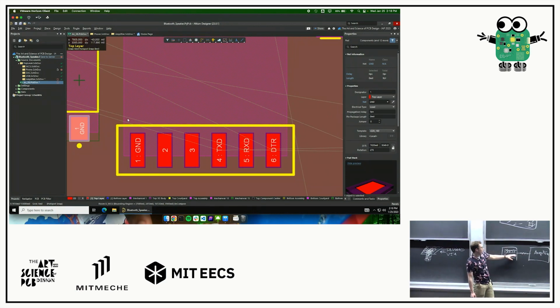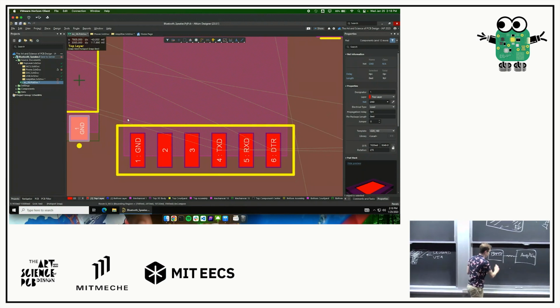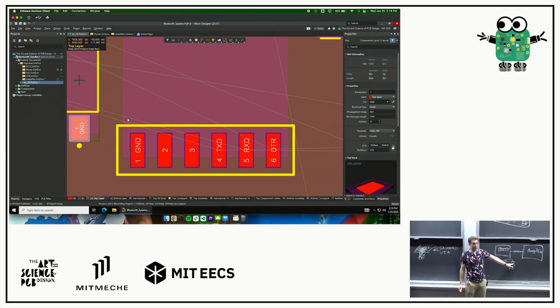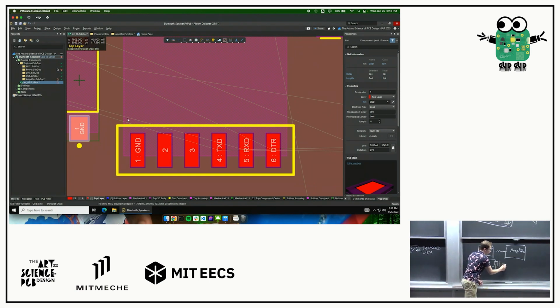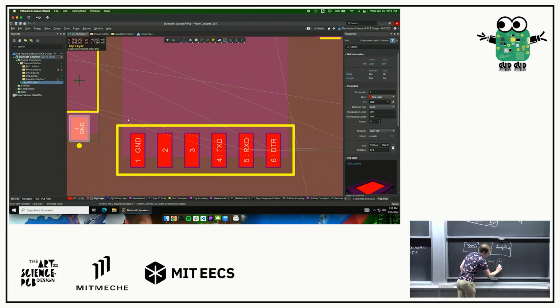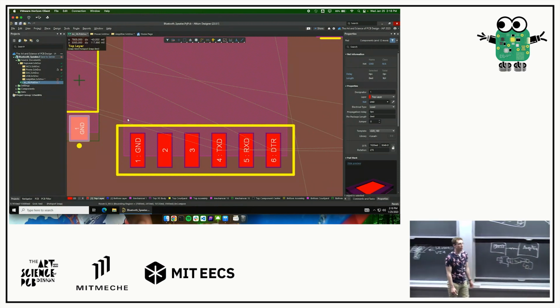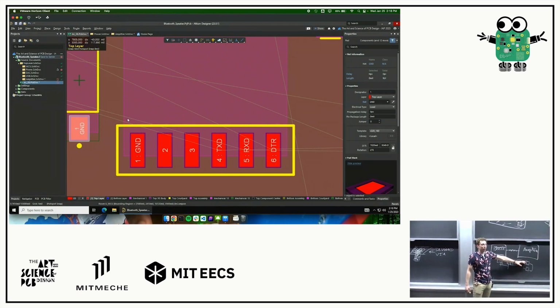Let's say that the output on our boost converter is, well, you know how we had that inductor? It's got a little pad there and a little pad here. Well, these are physically large, right? I think this one is something like 50 mils. And then over here on the amplifier, we have our big capacitors for bypass, right? So that'll be maybe here or something. What we could do is just do a 50 mil trace from here all the way over here if you want. That'd be a reasonable cause for making it a bit larger because this carries a lot of power.